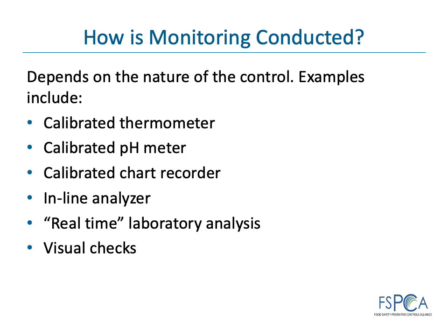Brix measurements, moisture content, water activity, antimicrobial concentration measurements, and other types of tests may have application in a food safety plan. However, lengthy analytical tests, such as many microbiological tests, are not useful for routine monitoring because critical limit failures must be detected quickly and an appropriate corrective action instituted before product is shipped.